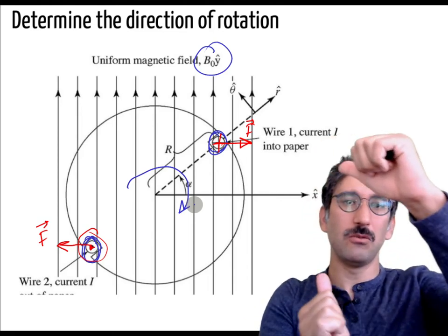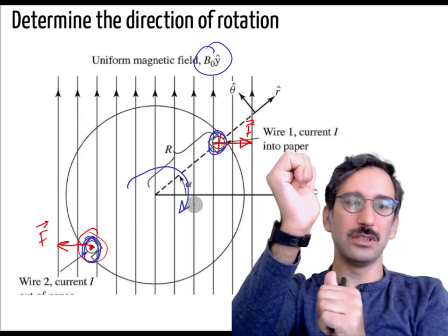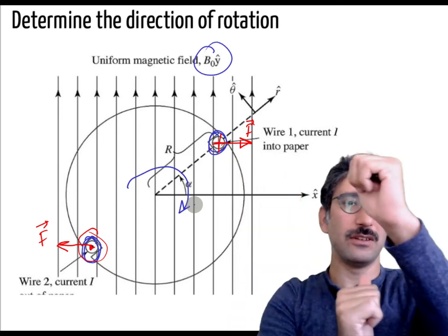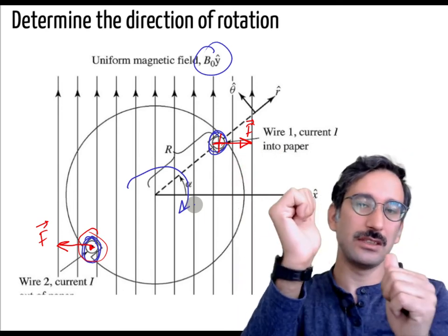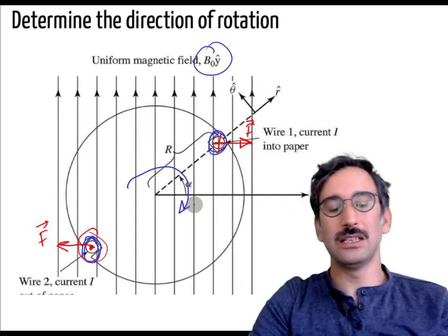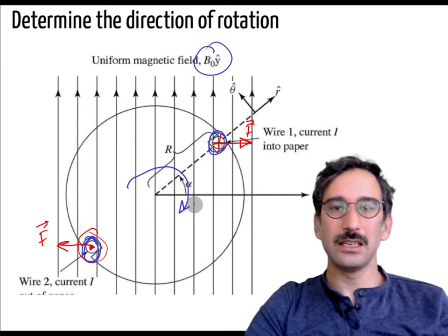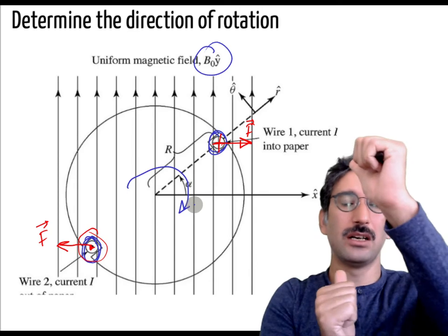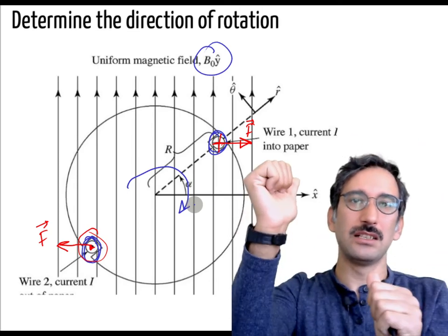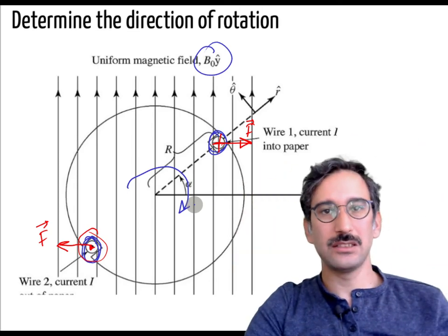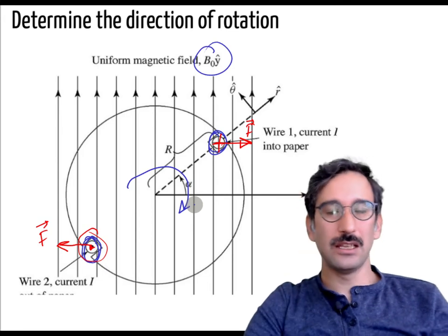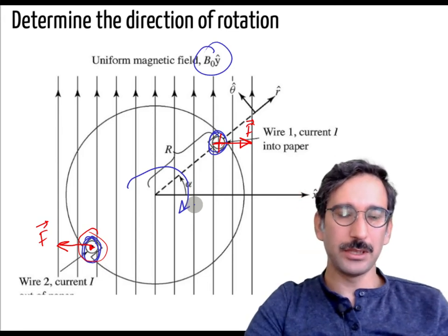Once it has moved, it will pull back, so it will actually make some oscillations, and if there's any friction, it will stop at a certain condition. But what we have in DC motors, if you remember, is that once it goes over some degrees, there are commutators in the rotor, and the direction of the armature coils reverses.